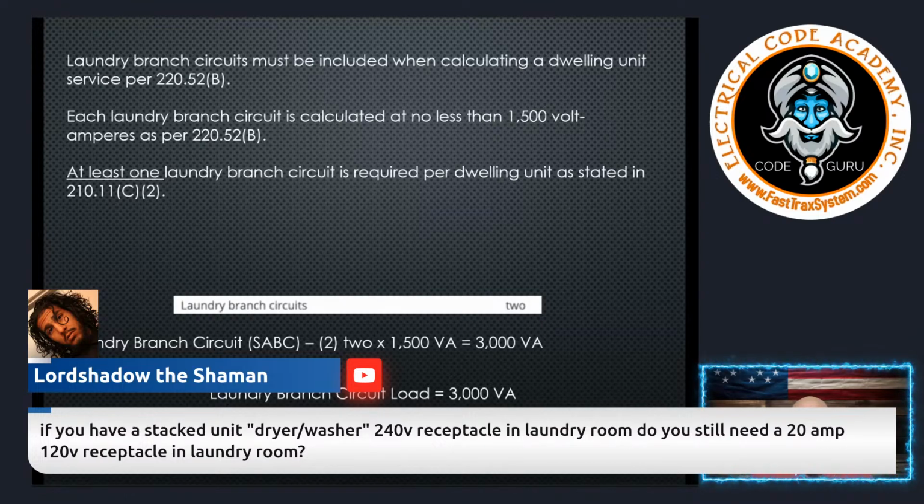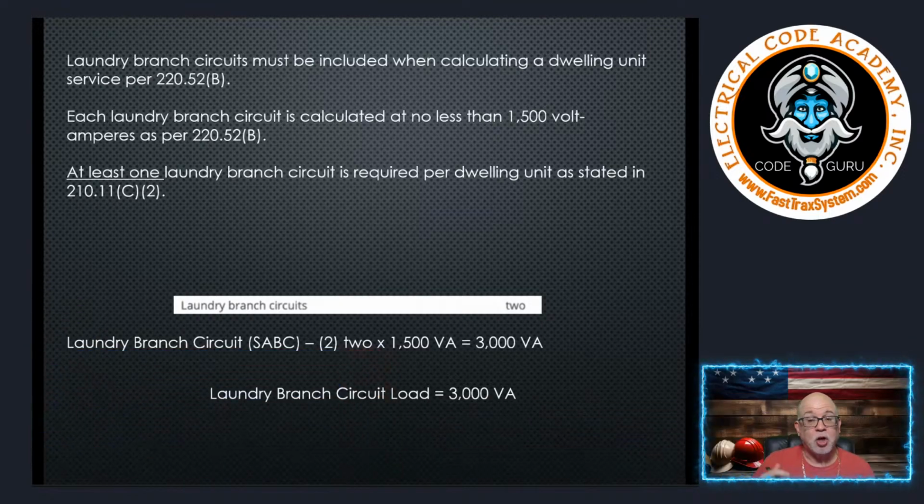There is nothing in the NEC that requires a dryer circuit, a 30 amp dryer circuit. Now, obviously, if you're on an exam and they give you a dryer, then you have to take that into consideration because they gave you the value. In fact, we do today on ours. But you're not required to put a dryer in. You're not required to calculate for a dryer unless, of course, it's being used. And if it is, then you have to apply it.